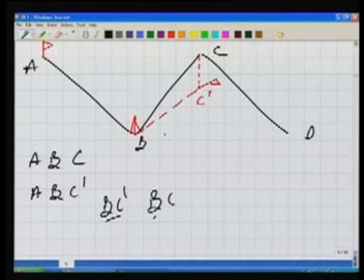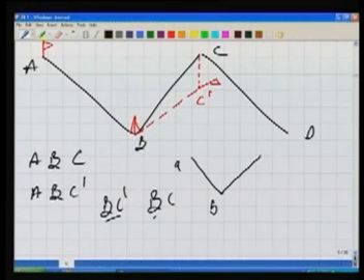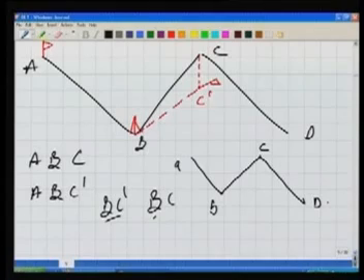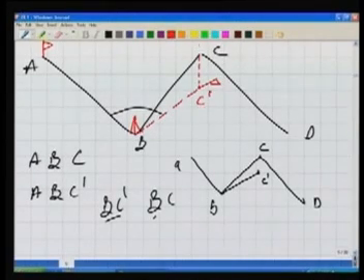Now what will the effect of this be? If we plot this survey on our drawing sheet, the plot will start with AB. Now at B we are making the angle ABC dash. So instead of going to the actual plot, the actual plot would have been C and D. What I am doing is plotting now the angle at B, which is the wrong angle, larger than the actual angle. So I plot it in this direction. So the point C dash is plotted here. It is not really C dash, it is C, because we did not know that we are making the miscentering error. And then after this step, we take our theodolite to point C.